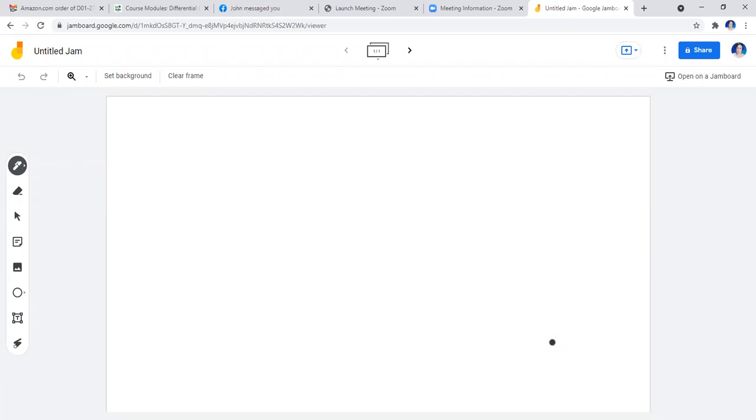Now, since we're given an RC circuit, you're going to start with the model DE for that RC circuit. So it was shown to you a while ago that our model DE is dq/dt plus 1 over RC times Q, and it's equal to E, which could be a function of time or it could be a constant, over R. Okay?